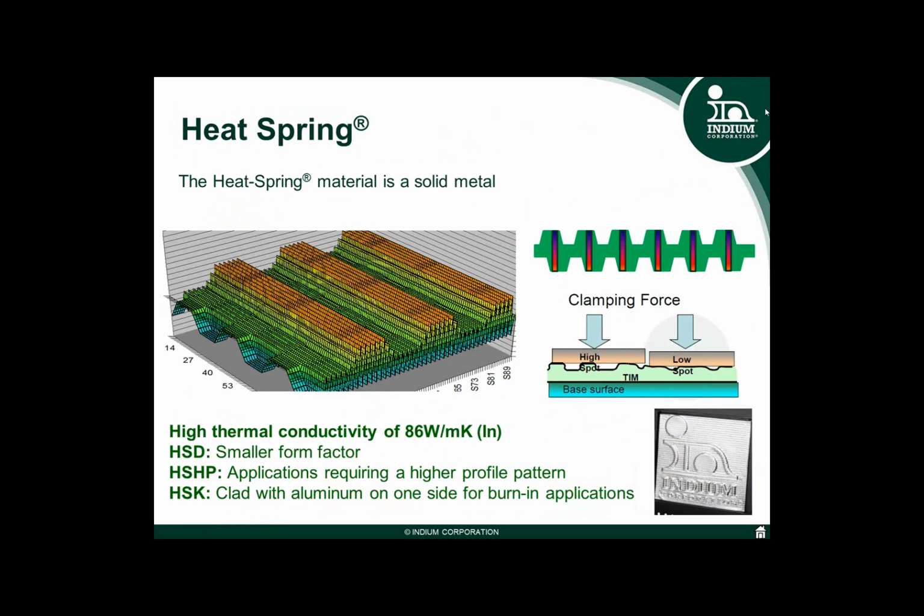The material itself has a high bulk thermal conductivity of 86 watts per meter Kelvin, which is massive in terms of metals. But with this, indium itself is a compliant, ductile material, so it's easy to shape.